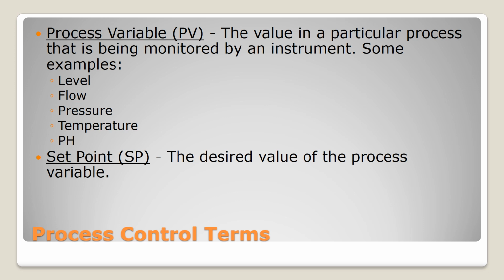So here are our variables. Most any power system, any manufacturing system, can be designed to achieve its desired function by monitoring these 5 points. There may be lots of different levels and lots of different temperatures and lots of different flows, etc. But these 5 parameters, level, flow, pressure, temperature, and pH, are going to be the things we're going to monitor.